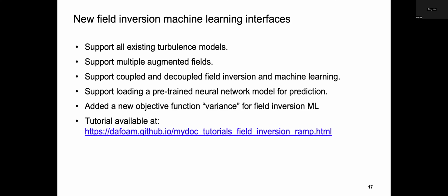Okay, yeah. So OpenFOAM has the capability to do transonic flow, but it's not using, for example, the Roe scheme or some other shock wave capturing schemes. I personally ran a few cases, for example, the RAE 2822 case, and the agreement between the DAFoam solver, which in this case is rhoSimpleCFoam, and some other solvers, for example, ADflow results and SU2 as well, is reasonably good.